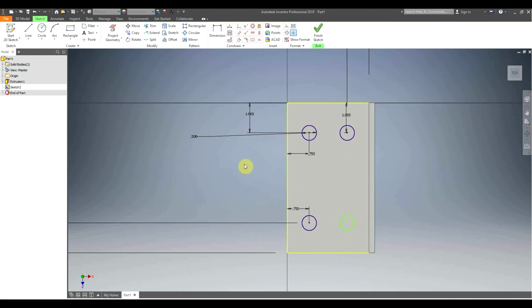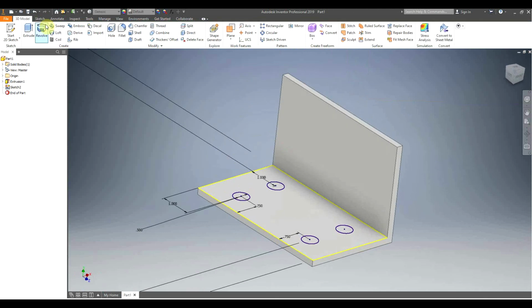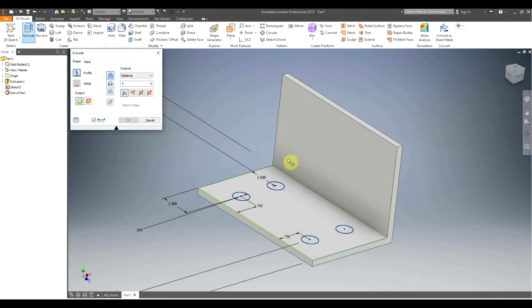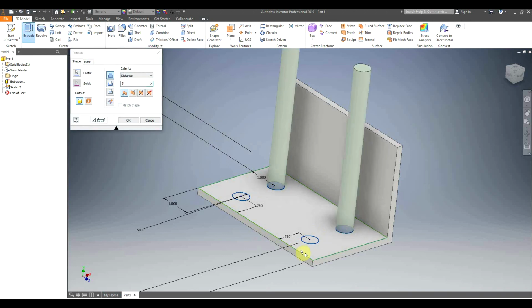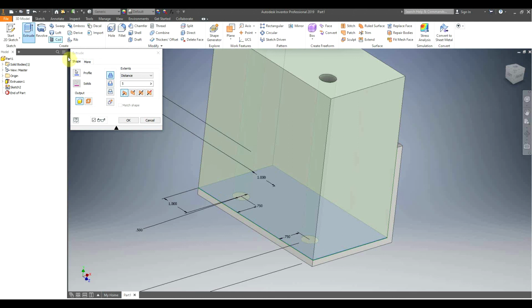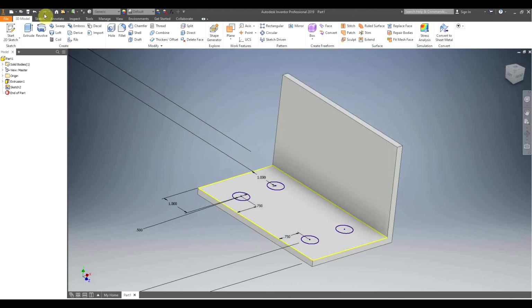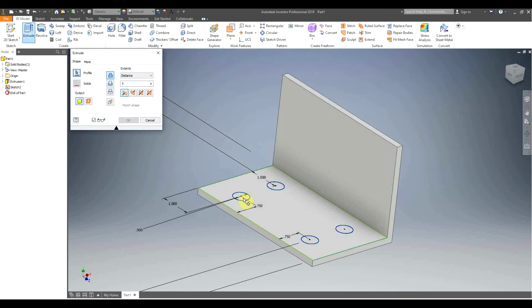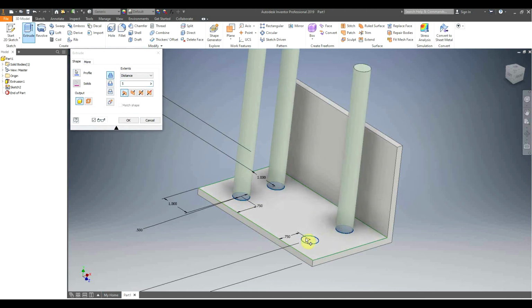So if we do that right there, go back up here, hit the horizontal constraint, and boom, fully constrained. So let's click Finish Sketch, go over to here, and click Extrude. Now you want to go on the inside of each one of the circles in your sketch, not like that. Click Cancel, back to Extrude, up here, there, there, and there.